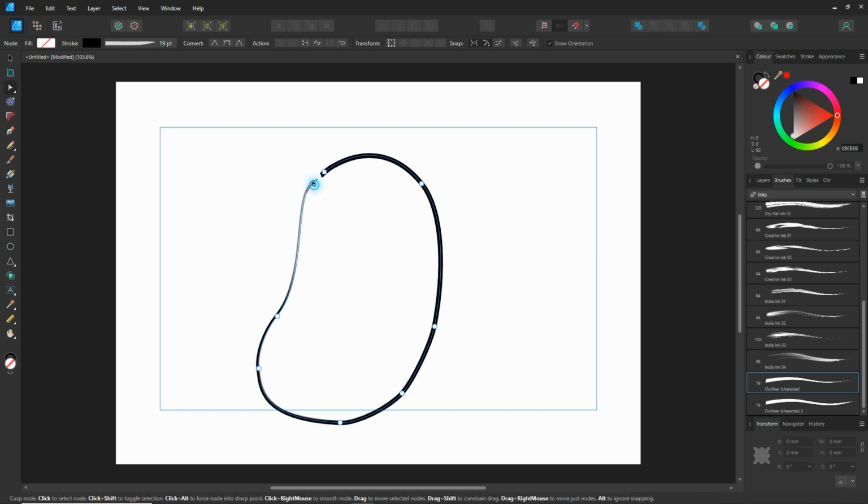While we're on the subject of nodes, as a general rule of thumb, something to keep in mind, as with 3D meshing, you only really want to be using what you need to describe the outline or the silhouette of the object. It's the same with 2D as it is with 3D, so all of these extra nodes that are part of the outline, if they don't aid the process of creating that outline, that silhouette, just delete them. Don't leave them in place, because all that does is make it more complicated and messy than it needs to be.